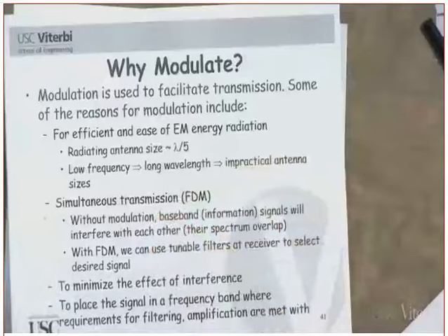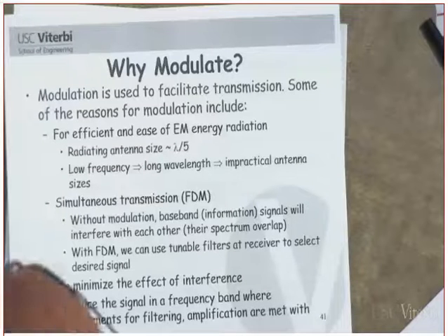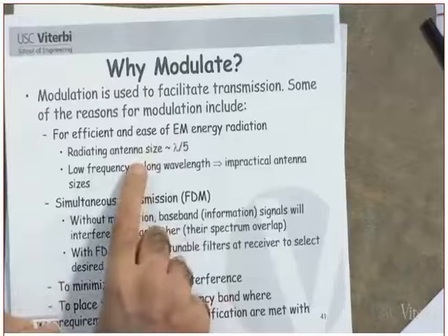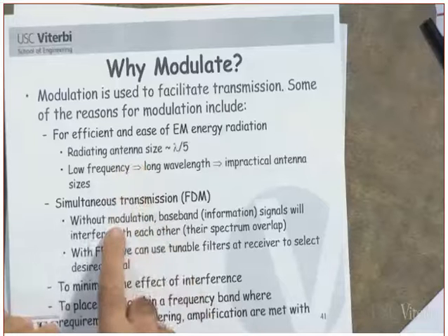So if you are not using modulation and you are transmitting a baseband signal with frequencies below 20 kilohertz, the size of your antenna will be in thousands of kilometers. Or you are going to carry an antenna thousands of kilometers on top of your head? You will become like the hunchback of Notre Dame. Are you following me or not? Clear?